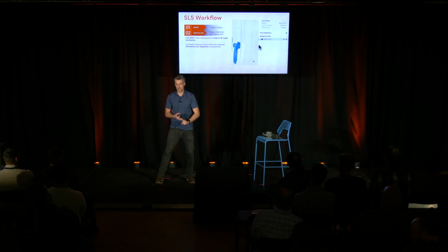One, when you want the XY scaling, you're going to want that often, or I often use it when I have circular things like these gears. I want the gears facing up at all times, the circles facing up, and I want the gear edges also facing up. So if you use XY scaling, it can rotate, and it won't rotate around the XY. But on the other side, if you want XYZ, you might want that in a case where you're doing nylon 11 carbon fiber, and you have directional strength there. You want to make sure it's not rotating about the Z either. So you're going to use XYZ rotation locking to make sure that it's keeping the same rotation, the same orientation that you've chosen, but it will translate around the build chamber itself.